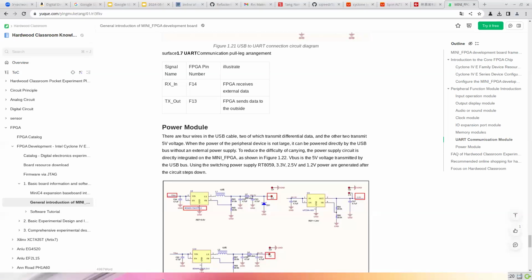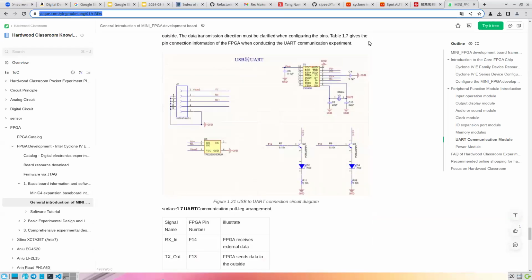You can look at this manual and then come up with any pin naming as you wish. But we need to keep two things. First of all, we need to give the user all the GPIO possible. And second, it should be consistent with another board. So if you want to make it consistent with MDAS, it's okay. We can keep it consistent with MDAS. And another thing: if you do any negation, any complement, this should be done before lab top or lab key or lab something.